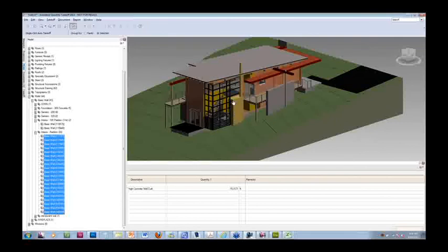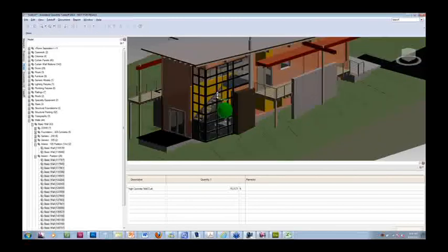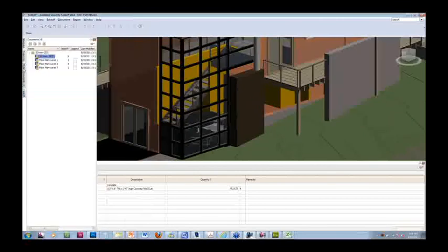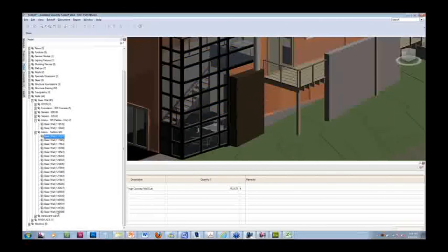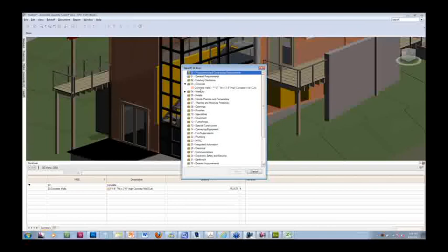You can select them all. It highlights them all in the model, as you can see here. I don't know if you see them in yellow. Let me zoom in a little closer. If you notice here, all the walls you select are being selected from the palette here. So what I mean is, once I grab all these walls, I can right-click, and I can take them off to an item. This is great because it's an additional feature that allows you to map these items to the category that exists for them to be now concrete walls.